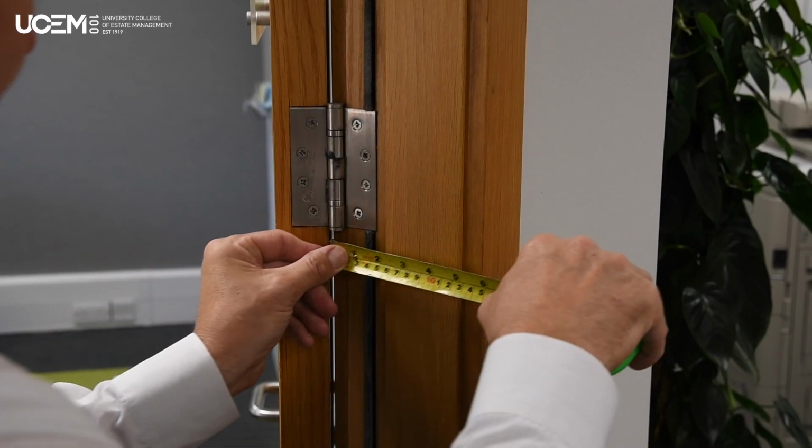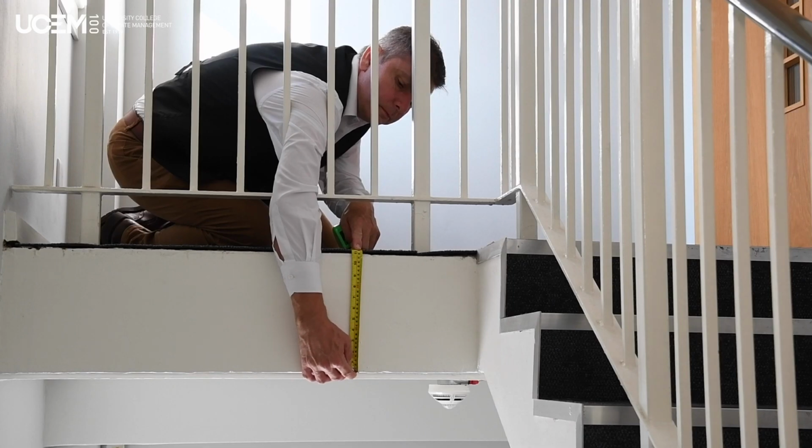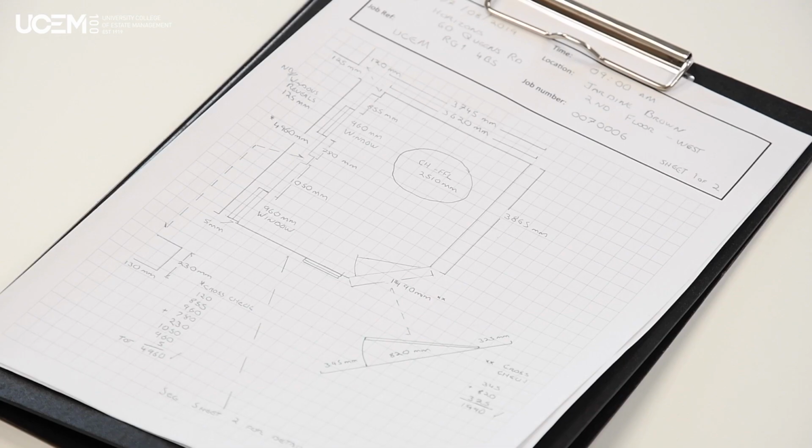If you need the thickness of walls and partitions, these should be measured at door openings. The floor thickness can be measured at staircase openings and in riser cupboards. Remember that the measurements are important here, not the drawing. As long as the diagram is clear and the numbers correct, you don't need to produce a work of art.